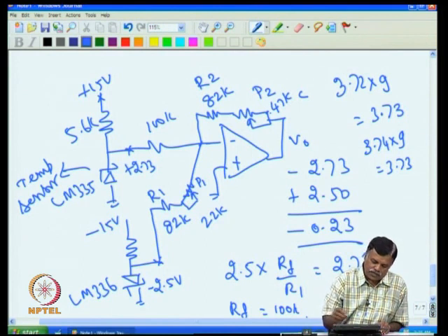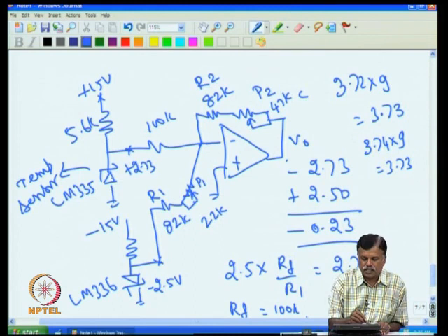So now what I do is I will put this one at 100 degree C and adjust P2 to get 1 volt. Then I keep this at 0 degree C ice, then adjust this P1 to get 0 degree C. So like that I should repeatedly do 3-4 times. That is, first I keep it at ice, adjust P1 to get 0, then keep it at 100 degree C, then adjust P2 to get 1 volt.